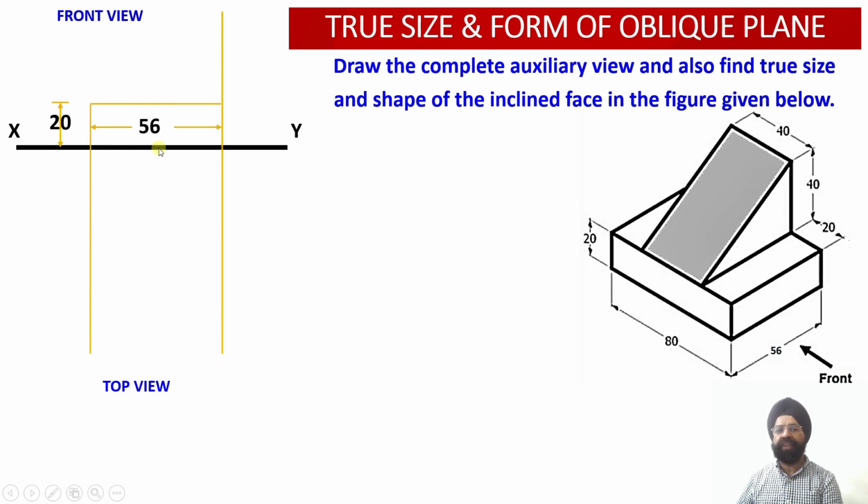With the construction of this rectangle, we are able to observe this particular surface of the solid from the front view. This is the true shape of this rectangular surface which has been obtained onto the vertical plane in the front view projections. Then we have surface number 2, which corresponds to the section portion of the solid. This is a triangular surface where the first portion, on the left hand side, the starting point of this inclined surface, is right here on the top surface of the web.